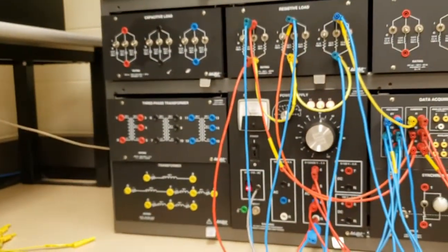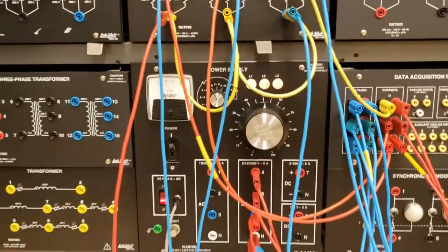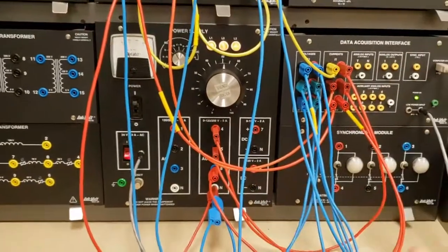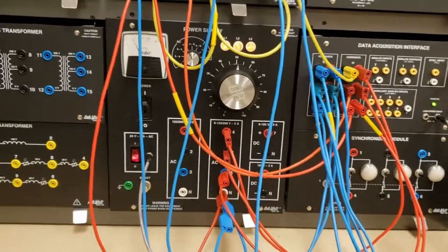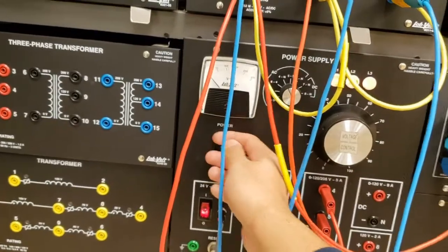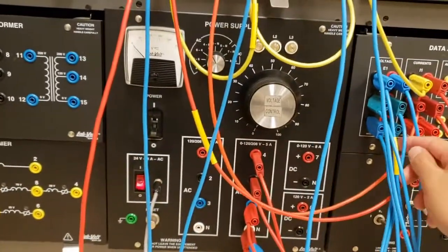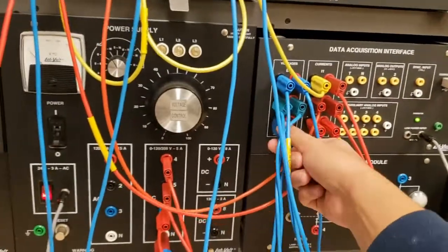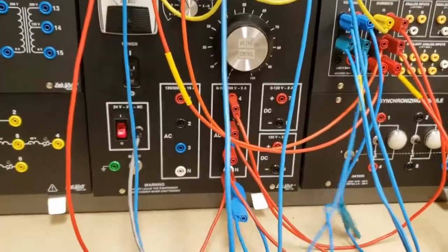Okay. And then the second part of the lab, let me remember here. Yeah. The second part of the lab basically has us, now that we've seen and confirmed that everything is three-phase, show what the difference between line to neutral and line to line is. So all I'm going to do is first turn the knob to 0, turn off my power supply. I'm going to remove E3, which is over here, because that's not important anymore.